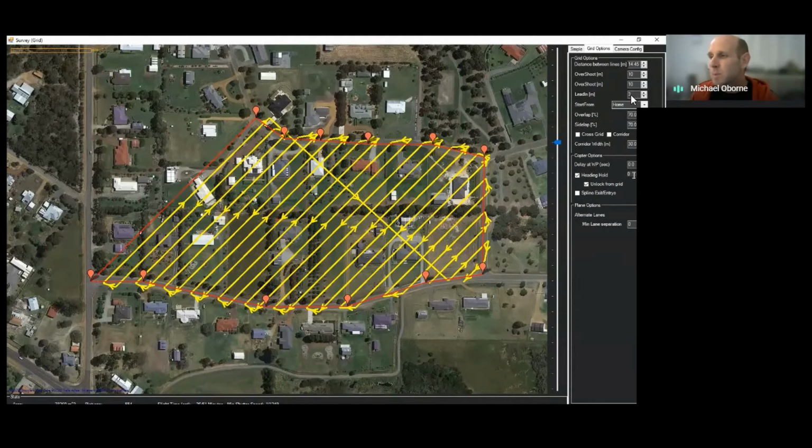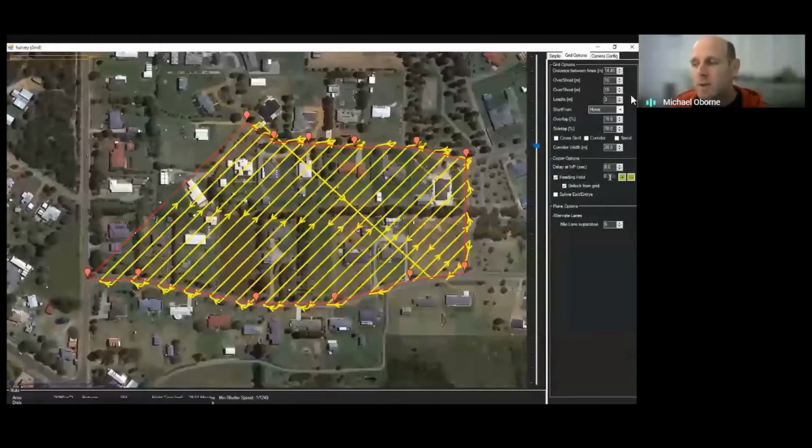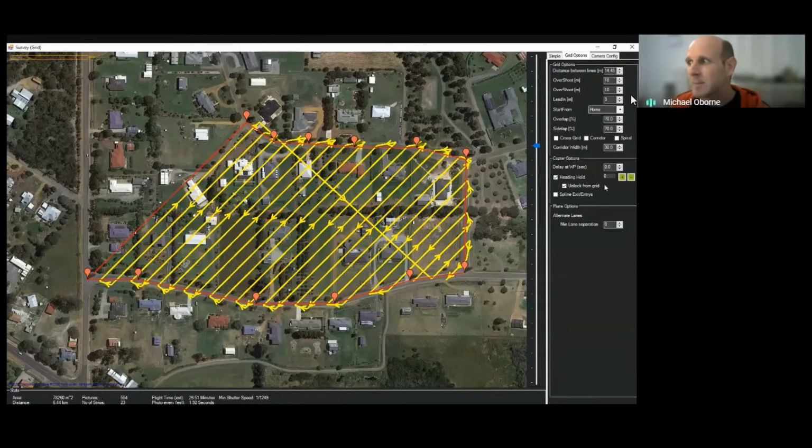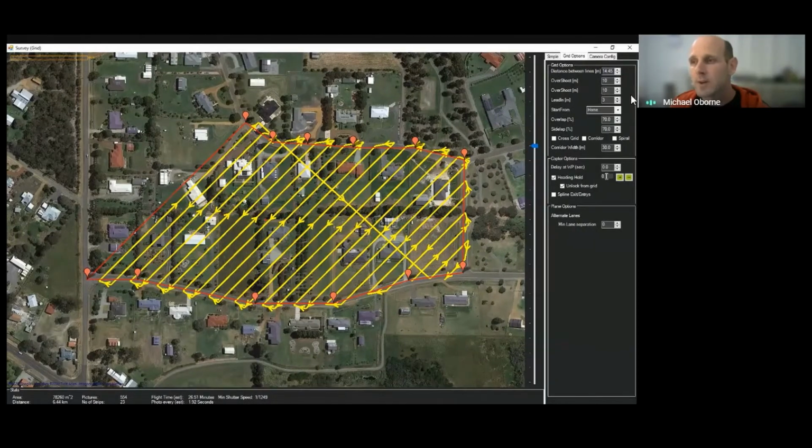So it's one way of making sure that the camera is facing a specific way, if you had a requirement for that, or if you were flying a different type of sensor, say a magnetic sensor of some description, that needed to always be pointing north. You can make the copter fly any direction you want and keep the copter itself always pointing north, but it'll just lean a different way to move in that direction. I'll just turn that off for a second.